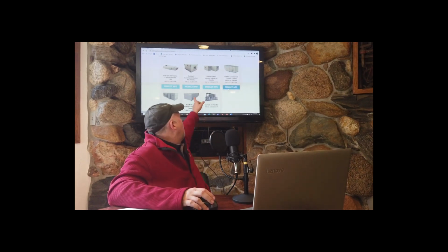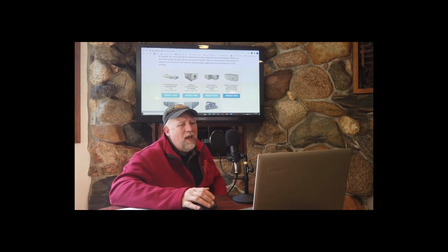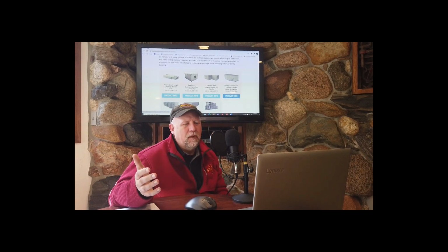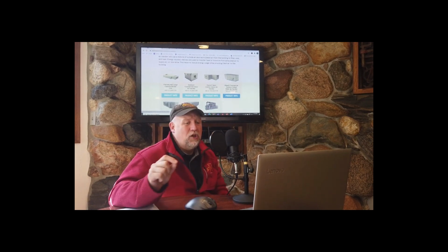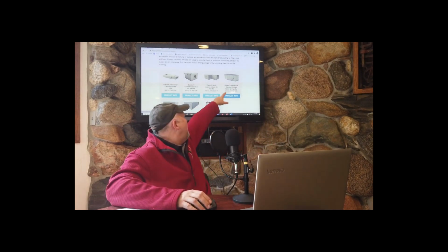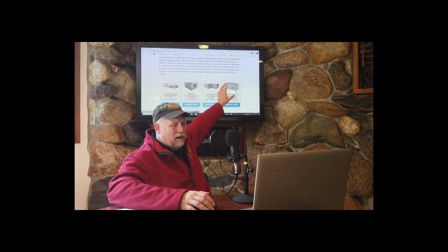I can't change everything about it, but I've got more options. Here, this Rebel commercial outdoor chilled water air handler. So it's meant to be outside, like up on a roof somewhere. It still is getting chilled water from a chiller somewhere. That means there isn't a refrigeration cycle within this air handler. It's not a packaged unit that comes all complete.